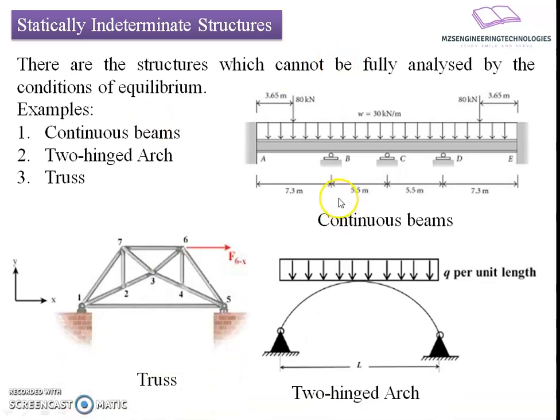In case of a continuous beam, we have n number of supporting spans developing n number of reactions, which can't be analyzed with reference to the available static equilibrium conditions, given the geometry as well as the loading condition. Thereby, unknown forces remain, which we have to analyze with the help of additional equations, either in terms of compatibility or with reference to constitutive relationships.